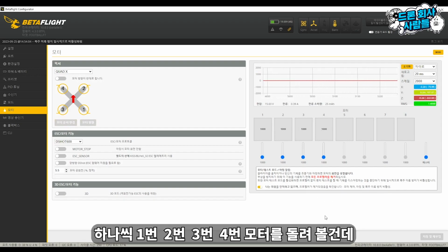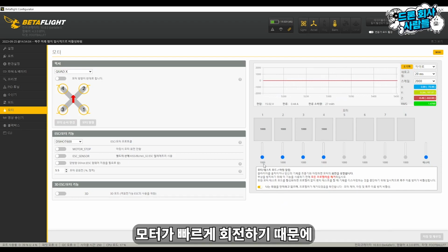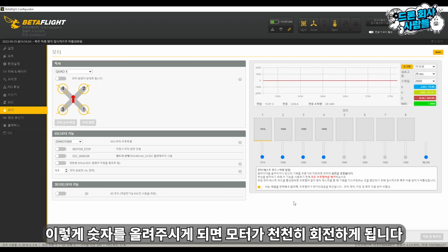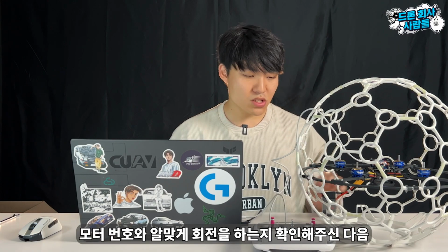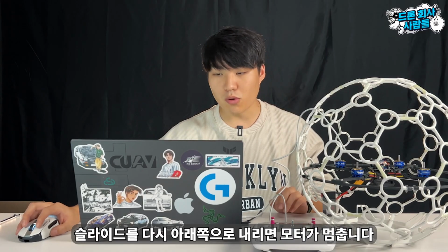Motor 1, Motor 2, Motor 3, and Motor 4. When you turn the motors, if you quickly push the slider up all at once, the motor will spin rapidly. So after clicking the slider once, use the arrow keys to increase the numbers, and the motor will spin slowly. Raise it to 1020 to check if motor number 1 is rotating correctly according to its number, then slide it back down, and the motor will stop.